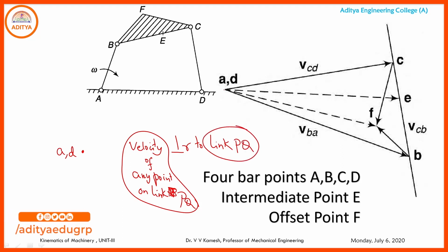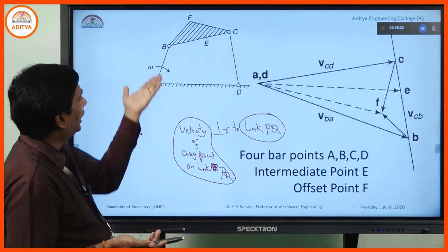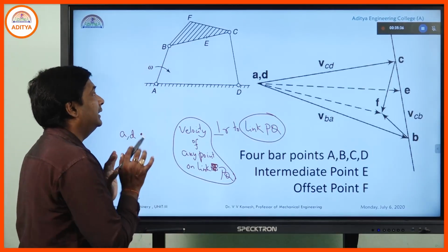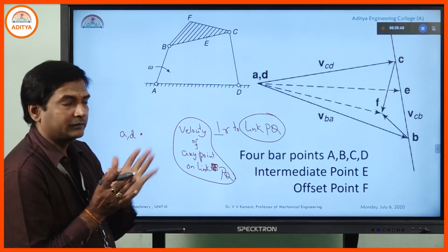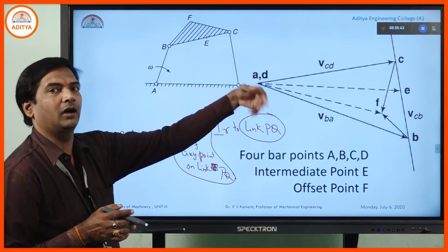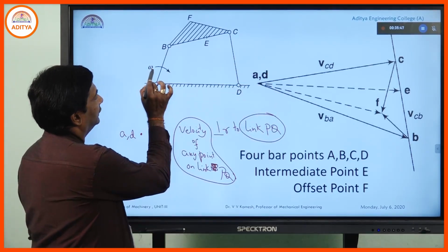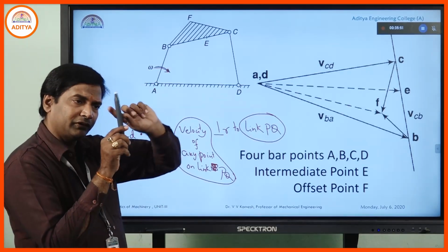Already we are supplied the length parameters in the diagram itself. So where will the velocities be? Always perpendicular to these links. Very easy, but the direction is primarily important. Secondarily, we will get all the directions automatically in the velocity diagram. Now, this is rotating in the clockwise direction. That means like this.